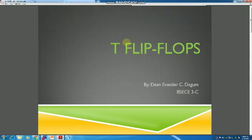Good day everyone. This video will show you the tutorial about the T flip-flops. In this topic, we will discuss the characteristics of the T flip-flop, its logic circuit, its logic symbol, the excitation table, and also the theory of operation. Then we will simulate the actual logic circuits used for creating a T flip-flop using EWB and demonstrate the operation of the T flip-flops.